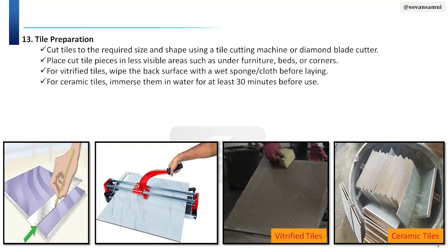Okay. And the third point is vitrified tiles. For vitrified tiles, we always wipe the back faces with wet sponges or any kind of cloth before laying. Or for ceramic tiles, we always immerse them into water at least 30 minutes before use.